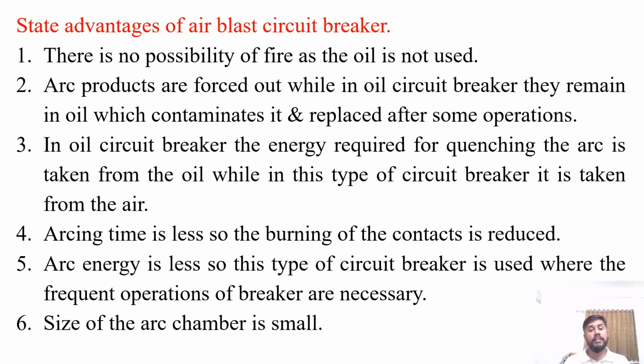So there is no possibility of fire as the oil is not used in case of air blast circuit breaker. Arc products are forced out, while in the oil circuit breaker they remain in oil, which contaminates it and it is replaced after some operations. So the arc products are within the breaker contact and the wear and tear and carbonization forms, and due to